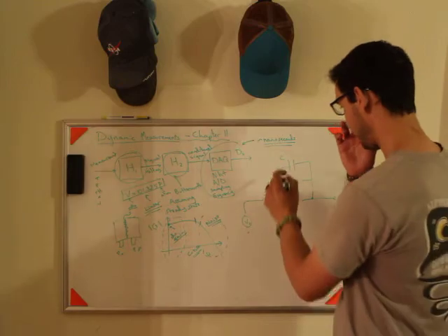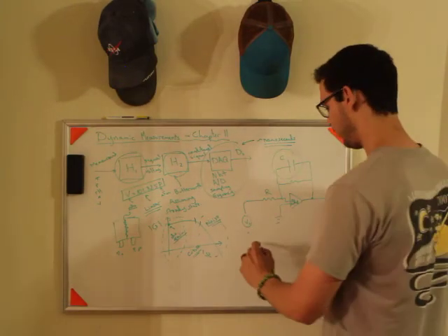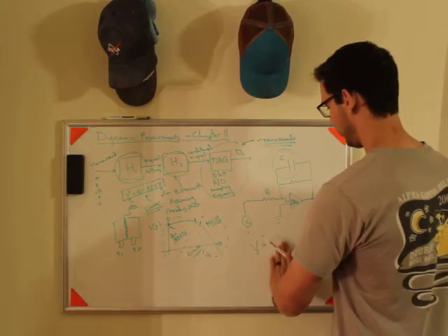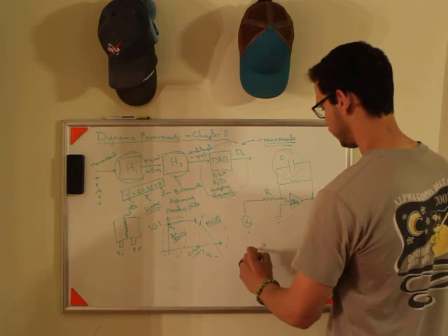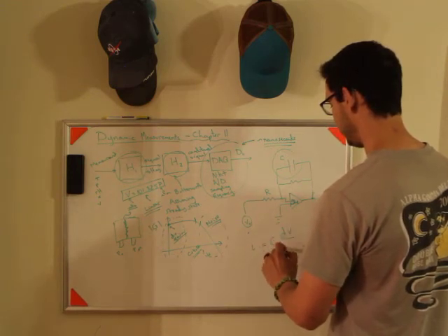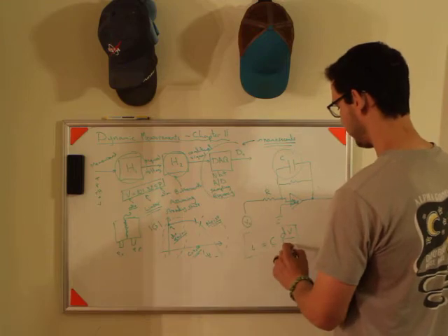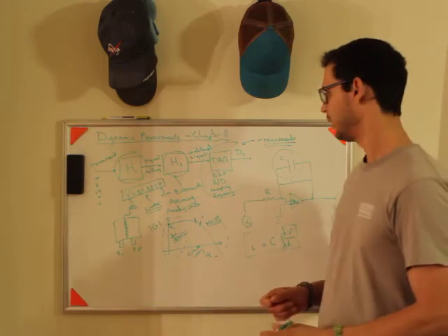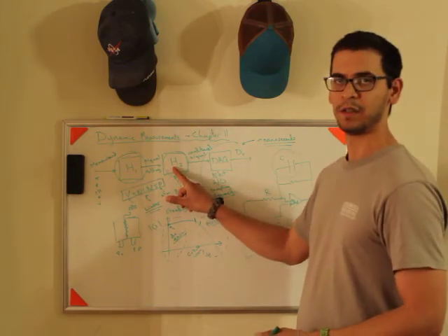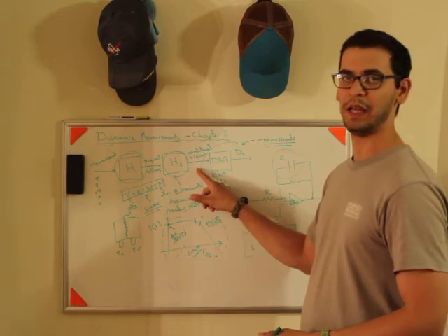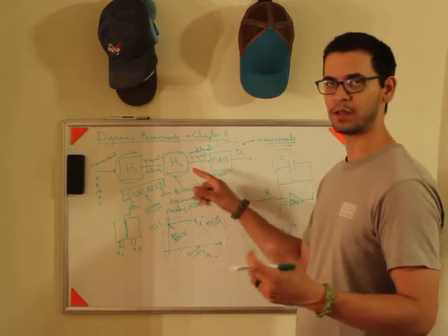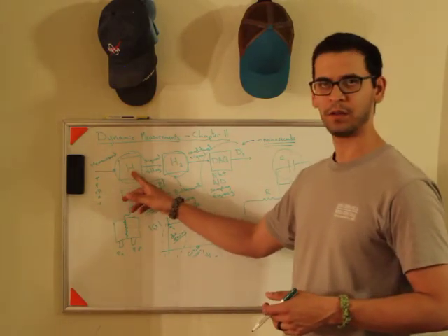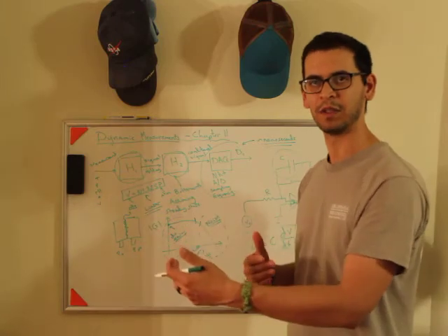The point is that this capacitor, if you recall, the current is equal to C times dV/dt, right? And so the current running through this capacitor is actually a differential equation. And so if you build a Butterworth filter, you're going to introduce some delay, and your measurand is actually going to lag behind your data, okay? And not only that, your measurement itself might take time to respond.